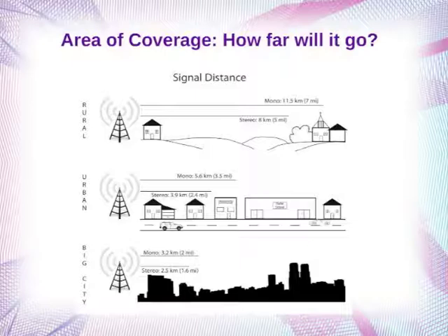There's a highly technical question about the clearest signal distance. Does it refer to the 60 dBu contour? No, it does not. Or to the co-channel first and second adjacent interference. It does refer to interference. It's the distance from your antenna where another station's signal would begin to cause some of your listeners to experience interference. It doesn't mean that they wouldn't hear your station. It means that they would begin to hear interference.